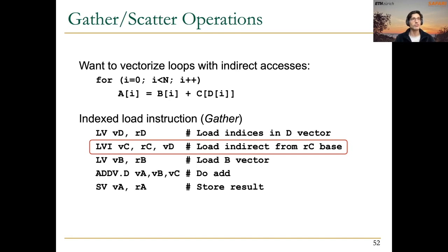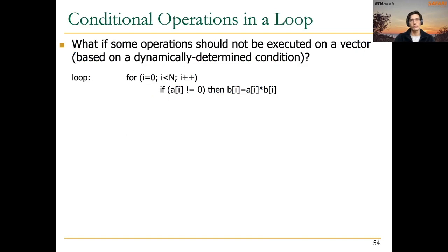That's what's going to happen. We are going to talk about bank conflicts soon, but we will focus on strided accesses that are probably easier to understand because they don't involve any array of addresses as array D here. But you will see that it's essentially the same thing. Of course, the most efficient way of accessing memory is when we don't have bank conflicts, when we can operate on all banks at the same time and exploit all the parallelism that the banked memory provides. But as I said, we are going to see the example in 3 or 4 slides. Okay, anything else?